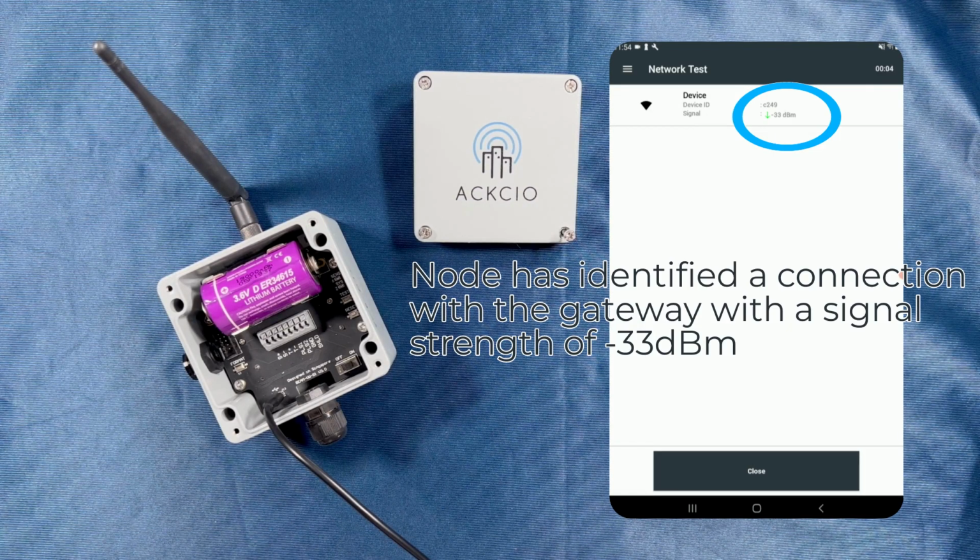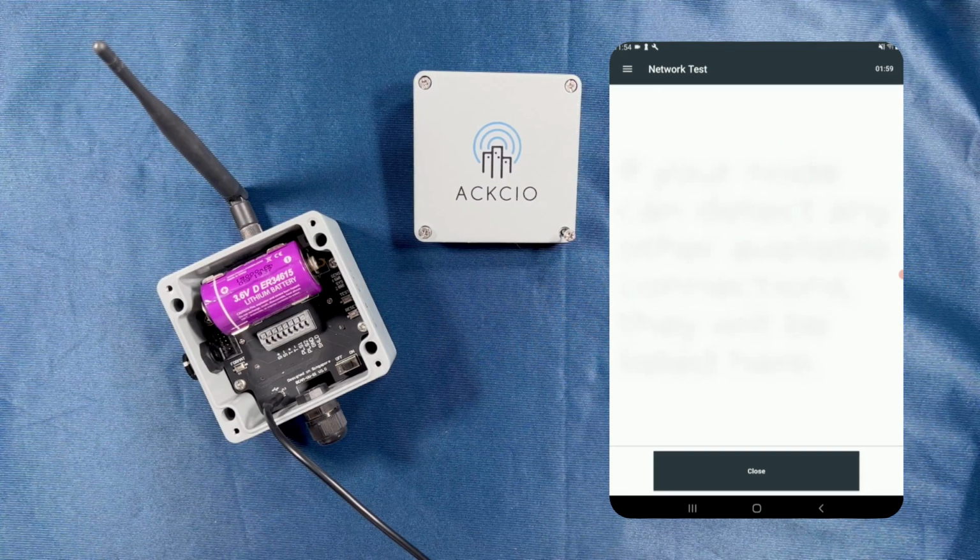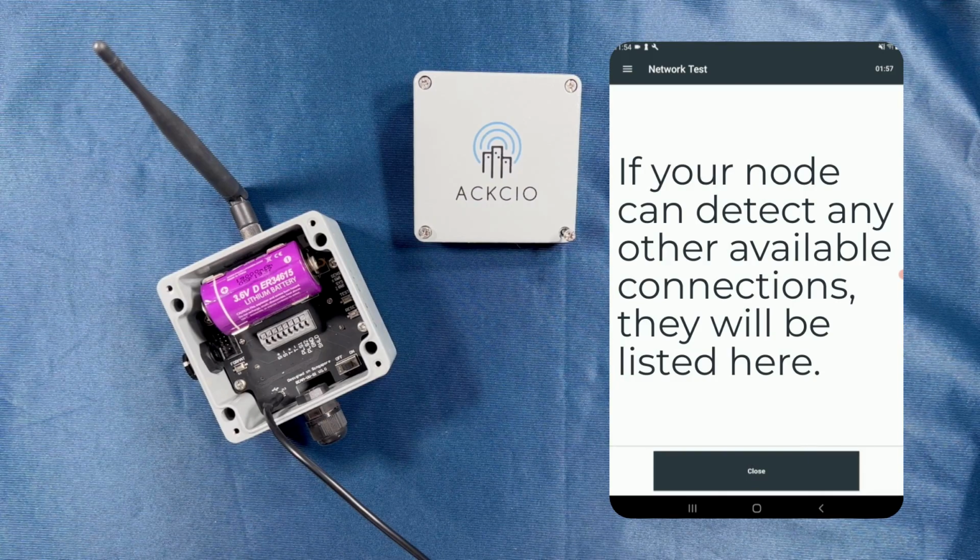Since this is the only node I've got paired to my demo gateway at the moment, I wouldn't expect to see any more connections. However, for live projects, we recommend that you see at least 2 available connections in this list to make sure your node has multiple ways to get the data back to your gateway.